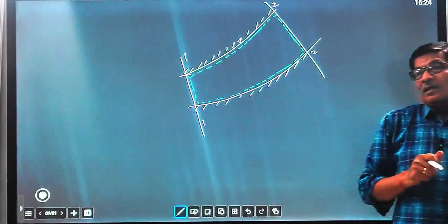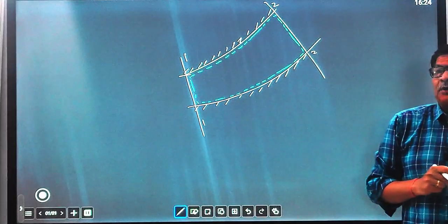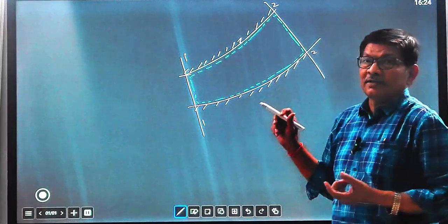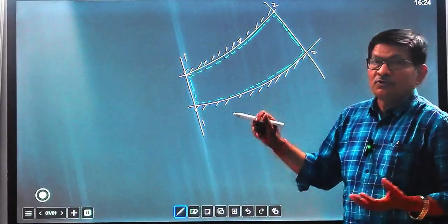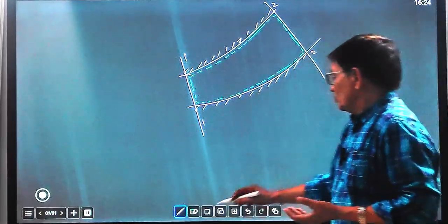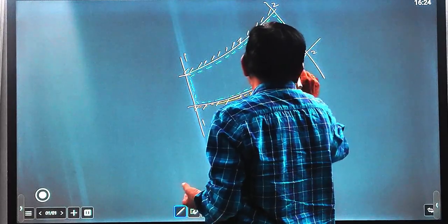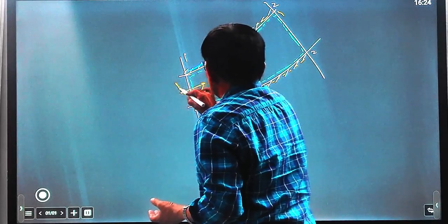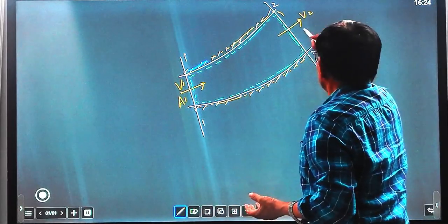As you know, in solid mechanics the material remains rigid, and volume and mass do not change while considering motion of the object. But in fluid mechanics the material is not rigid; it is expandable. Particularly in fluid, it may expand due to changing density, so mass will change. So we follow the control surface and control volume approach. Here is a control surface. Velocity at this point is V1 and area is A1. Velocity at this point is V2 and area A2.